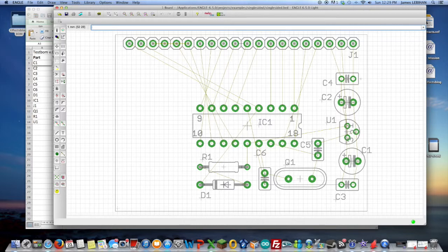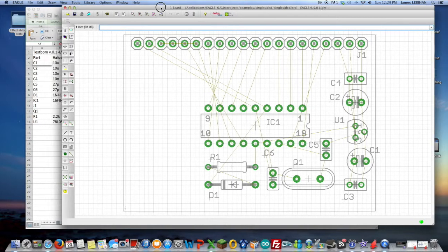With something like a ceramic cap or an IC or a jumper, I don't have that, so I have to be absolutely precise with this pin spacing. I also need to know the diameter of the holes so that I can make sure that I'm not getting a lead that is too big to pass through the holes. Okay, so those are things that we'll need to know before we go get the parts, and we can get that from the board itself or the drawing or other technical documents that you have describing that.